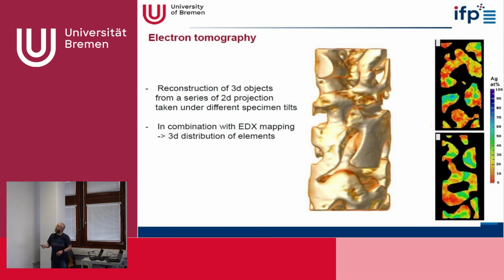Nanoporous gold is usually produced from a gold-silver alloy, and this gold-silver alloy is put into an acid, and this acid will remove the less noble atoms from the alloy. In this case, the silver atoms have been removed, and what comes out is such a nanoporous structure.